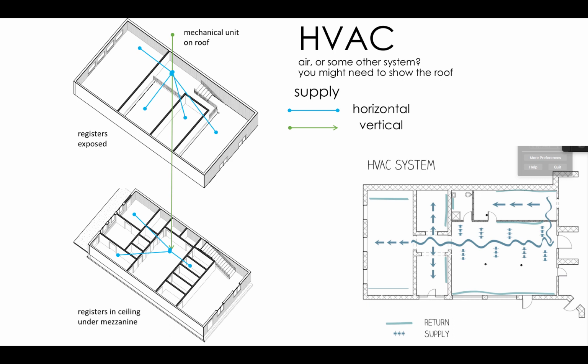You don't always have that kind of HVAC system, or if you're working in a project and you diagram it out, you're like, that forced air system is not going to work for us. You might need radiant heat with a makeup air supply, whatever it is. When you diagram this out, if you don't have anywhere to run those ducts, you can't have HVAC that uses ducts. You'll have to find some alternative system.